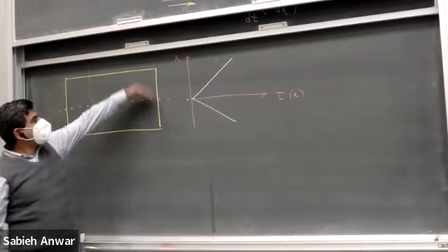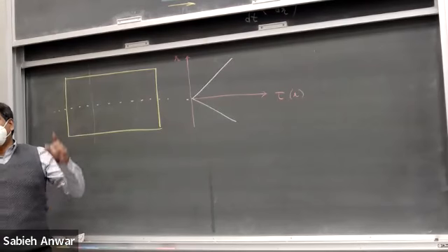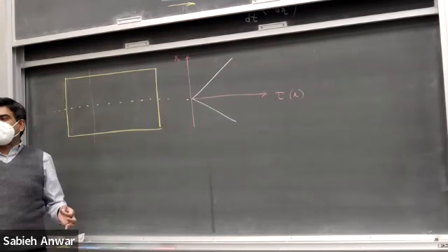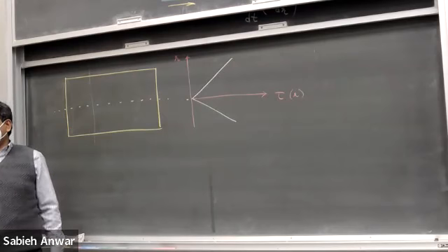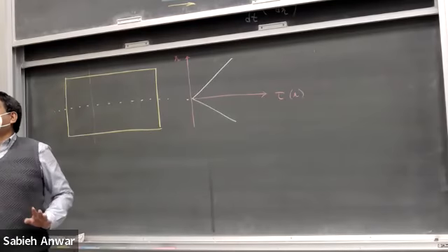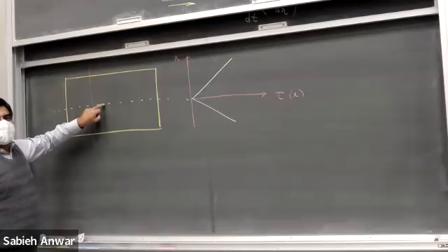Okay, so this is above the axis, this is below the axis. Forget about the negative sign for the time being. It's going to be on one side, right? r is just a radial distance, always positive. So the stress is non-uniform. The shear stress is non-uniform. The shear stress is maximum on the walls, and it's 0 over here.